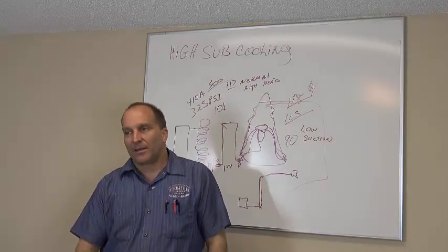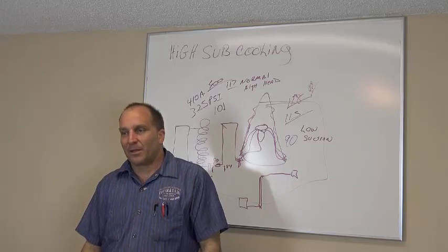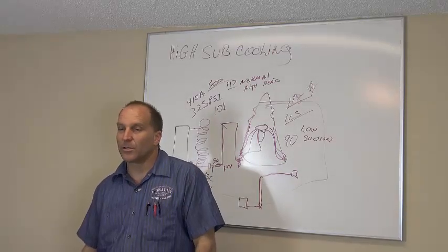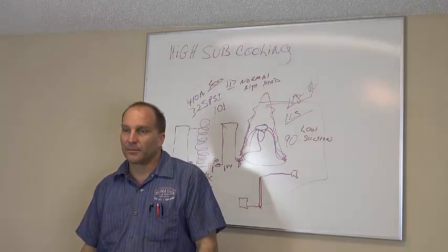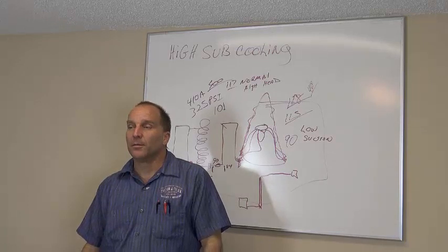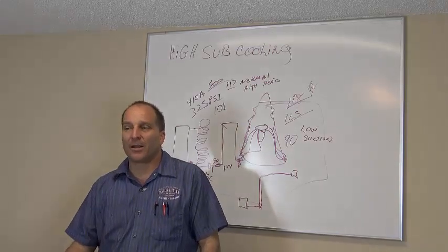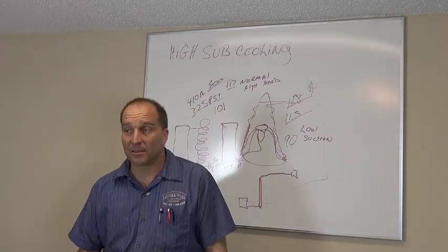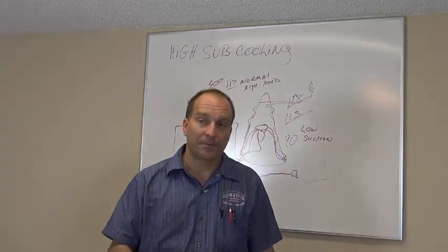After you put it all back together, you start the system up, and about 10 minutes later, your suction line's freezing back. Why is your suction line freezing back? Low refrigerant. Could be low on refrigerant, but it's probably not going to freeze back that fast from being low on refrigerant. Okay? Adam? The evaporator's dirty too.